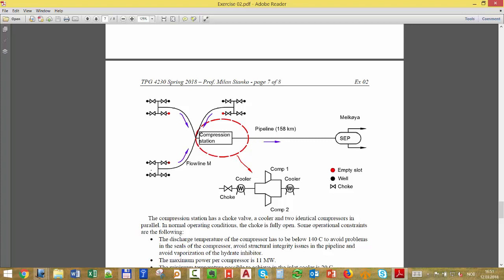No, we didn't have a compressor last week. This is a new thing. It's on the choke, right? That was where we put our equilibrium point. So we basically computed from the reservoir all the way to the wellhead, co-current. Our curve looked something like that, right? And then we computed from the separator all the way to the template.